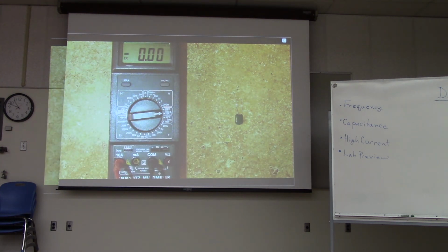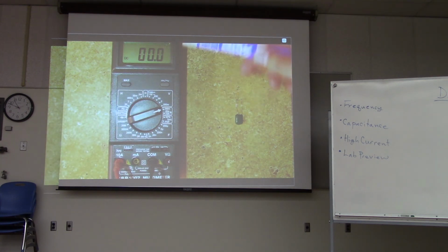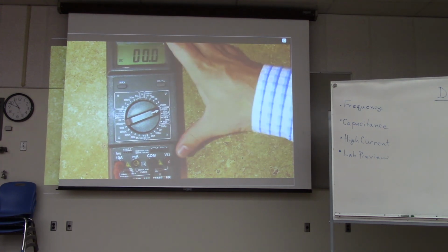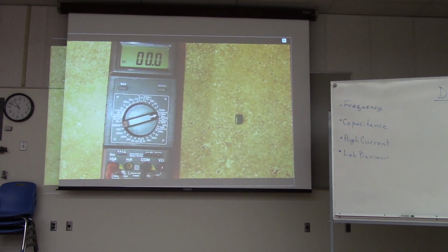What happens is that if you put it in this other spot, there's no indication to tell you that you're doing the wrong thing on the meter, but the reading that you get will be off by a factor of 10. It'll be 10 times too large, I believe. So there's no warning light that says you're doing something wrong. There's no other indication that tells you.